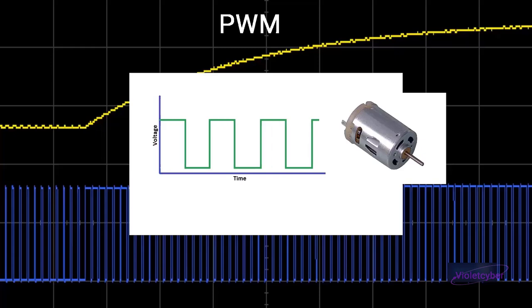If a 12-volt motor is used, and we have applied this PWM signal to 12 volts, the voltage that reaches the motor is 6 volts. So in this case, the motor is actually turning at 6 volts and is using half of its power. And if we increase the percentage of the on time, the motor speed will increase, because we have given the motor more time when the voltage is 1 than when it is 0.